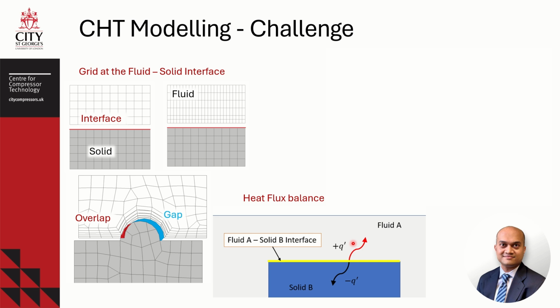So many solvers use a weak coupling in the form of inner iterations, where temperature from the solid is first applied as a boundary condition to the fluid. The resultant flux is then applied as a boundary condition to the solid, and by converging within an inner iteration, a final heat flux is then balanced to march in the time step. This requires special treatment in the solvers.